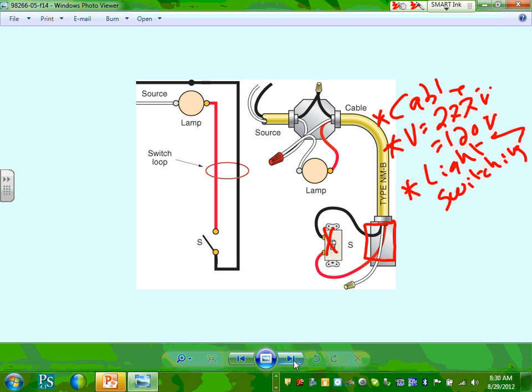What people did before is they tied it to the grounding system because they have a ground. By the way, the grounding conductor and the equipment grounding conductor, you're not supposed to use them that way, right? But they do the same thing. If you take a hot and an equipment grounding conductor, the light will get as bright as you can get it, because both of them are grounded conductors. But we use them differently. We use the neutral to carry the return current, and we use the ground to carry only fault current, ground fault. That's all, for safety.